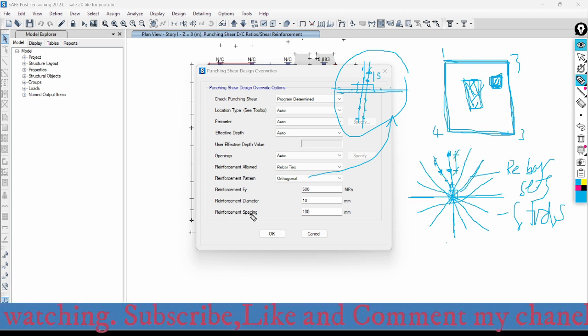So we need to specify the spacing of the rebar ties here in the orthogonal direction. That means this is S1 and this is S2. Here in this case we need to specify S1, because we are selecting the rebar ties with orthogonal arrangement. If I select the rebar ties with radial arrangement, this will be S2.